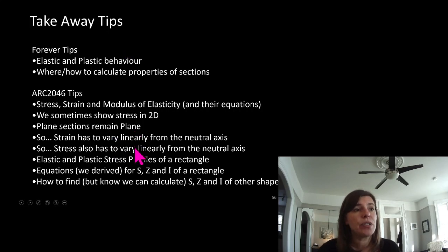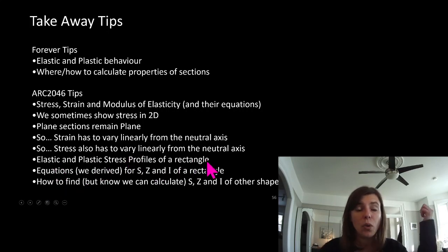For this course, your takeaway tips: you should remember stress and strain and modulus of elasticity and their equations. You should remember that we sometimes show these things in 2D. Plane sections remain plane. So, strain varies linearly from the neutral axis, which means that stress also varies linearly from the neutral axis. Elastic and plastic stress profiles of a rectangle we looked at.